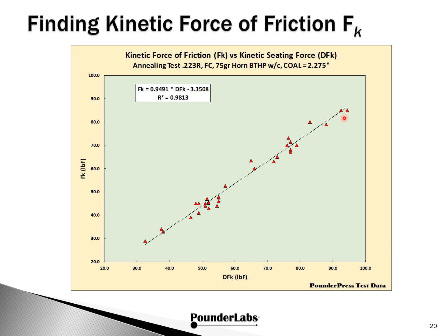All these again are just single-fire brass. And so what we want to do is get a very consistent value for hoop stress, and we like a nice tight cluster to give us the best shot-to-shot performance. Here's the equation between the two, and you can see from R squared that we have a very good fit.